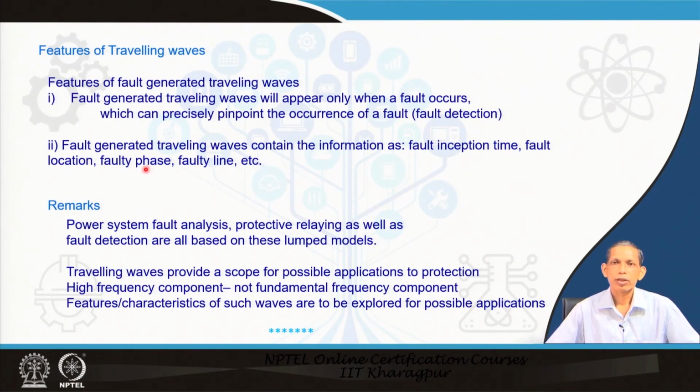The faulted phase can also be identified, because with respect to reference A and the others, where you get a significant amount of travelling wave will be indicative of that. And we can also identify the faulted line if it is a double circuit or multi circuit system. So, different features and characteristics are available that can be useful for different applications.